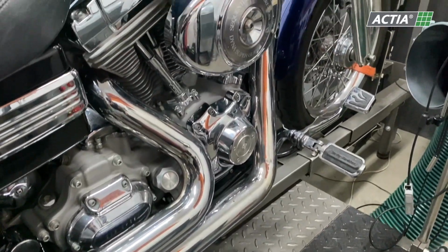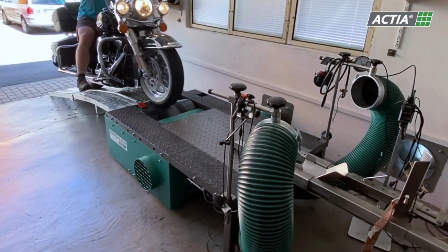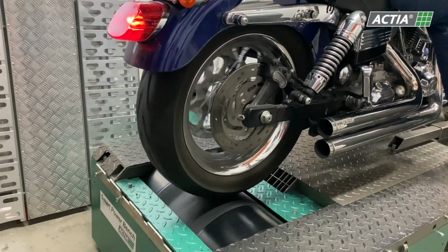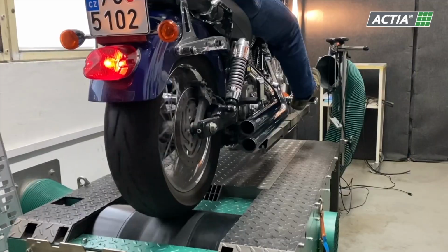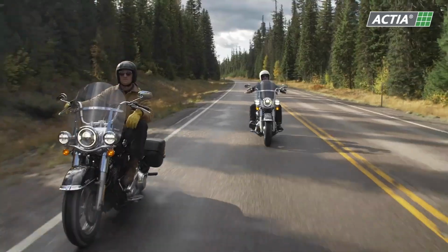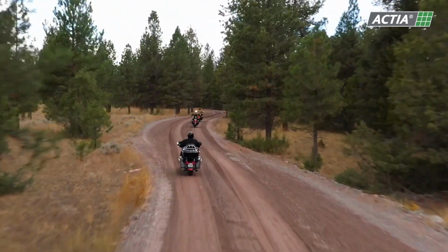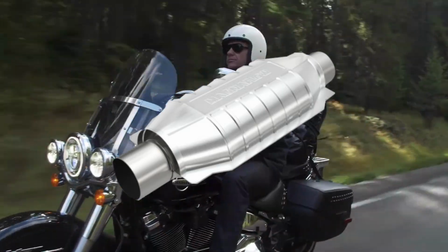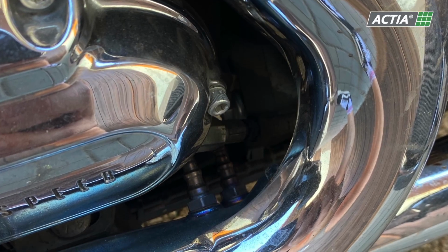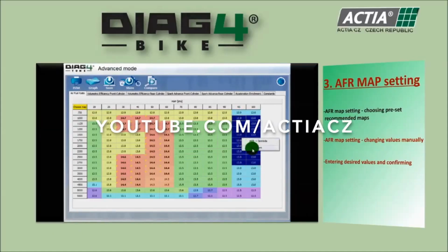The demands placed on a motorcycle engine by various regulations and by bikers are contradictory. A forced goal is to produce as little noise and emission as possible. However, technical measures that allow this limit the intake of air. This decreases the achievable performance parameters. The motorcycle manufacturer is forced to build motorcycles that meet strict regulations, primarily in terms of noise and emissions. This is achieved through various technical solutions such as installing silencers and catalytic converters in the exhaust, mounting efficient intake filters, and using sensors that evaluate combustion, for example oxygen sensors. The fuel maps of the fuel injection unit are then adapted to this configuration of engine accessories.